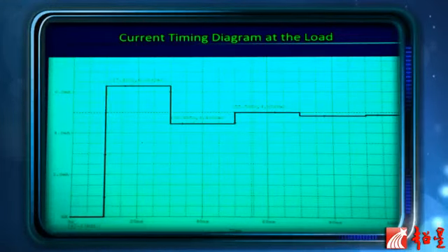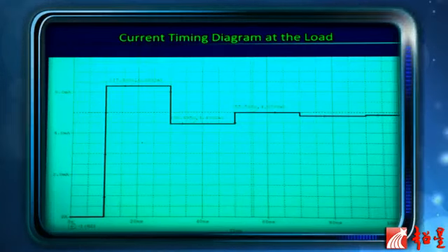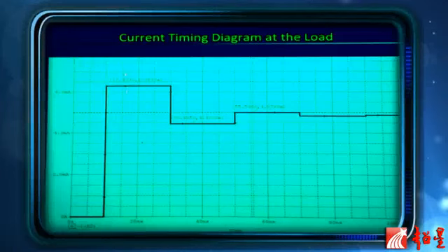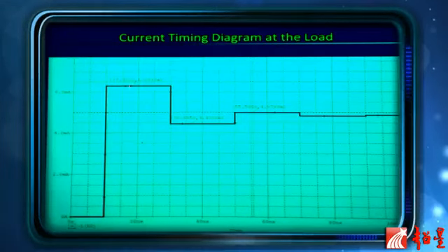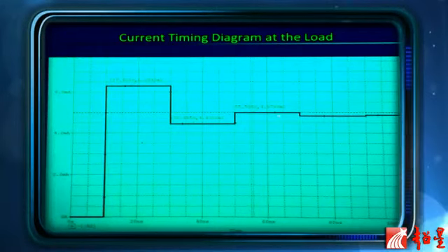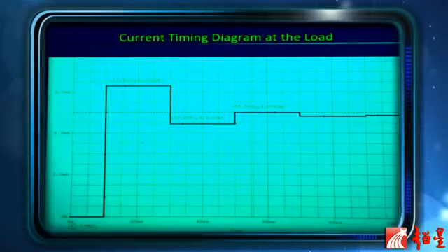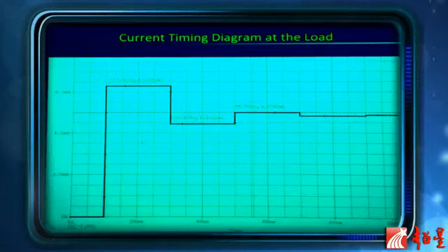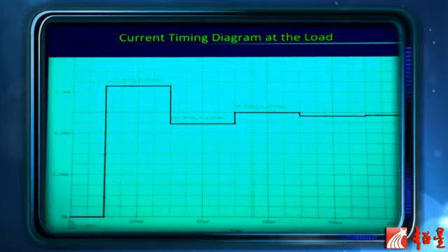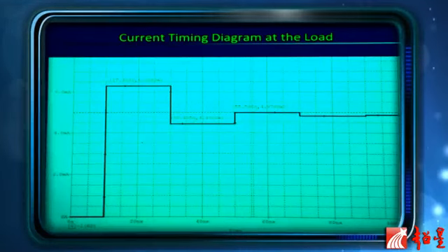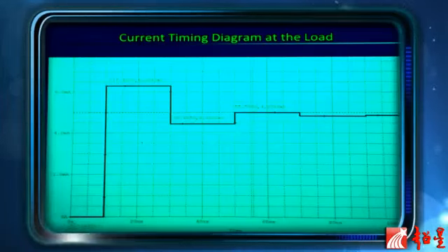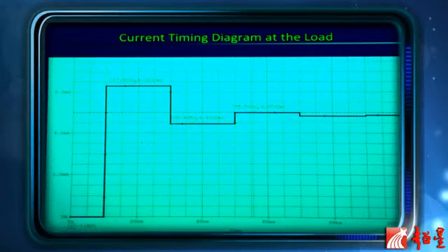So if you do that, once you obtain a simulation waveform, you should display the voltage values for each of these using display marker and then display values, so that your plot will have not only the waveform but also the voltage values. So you can compare this against your manual solution. And as you solve the homework problem, you should do the same.